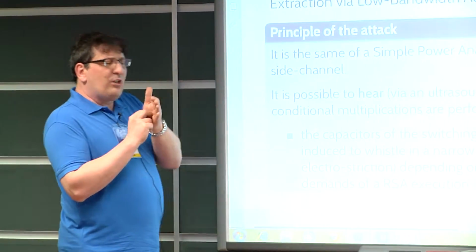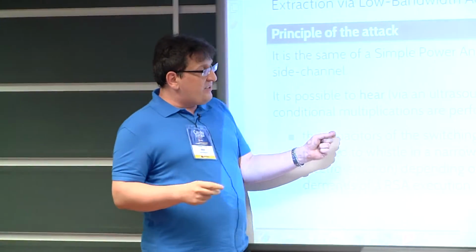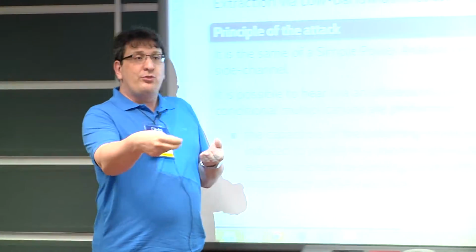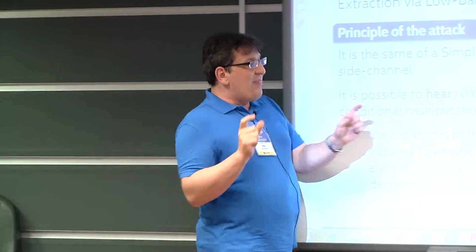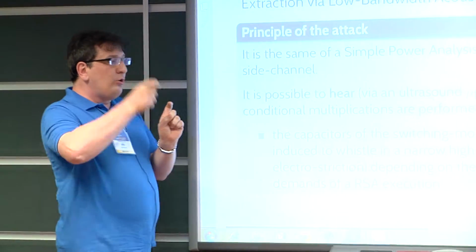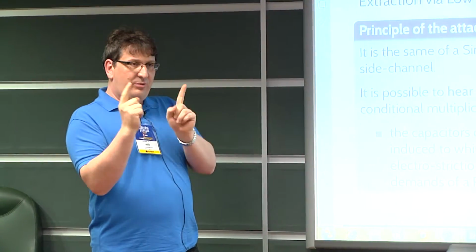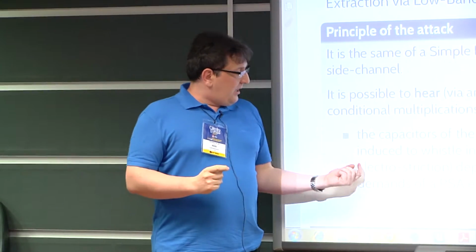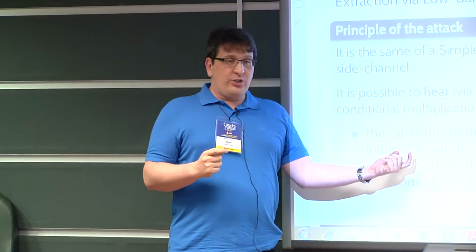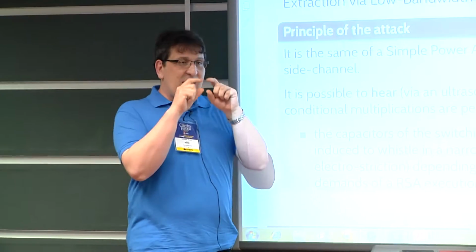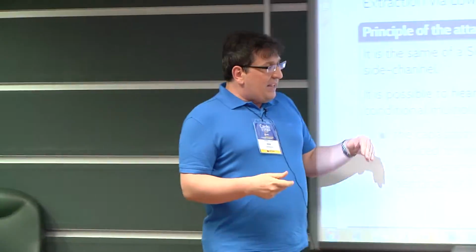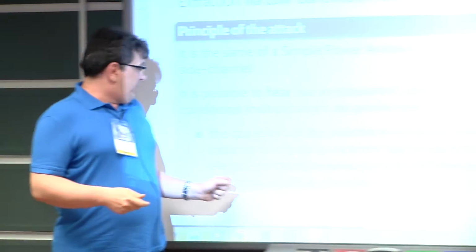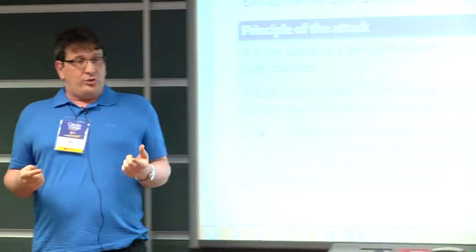The crucial observation of the authors of this kind of attack is that the capacitors of the switching mode power supply of your laptop are induced to whistle in a narrow, high audible, low ultrasound range due to the electrostriction phenomenon in the capacitors of the power supply module. Okay, depending on the different instantaneous energy demands of the RSA execution.